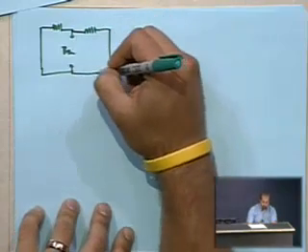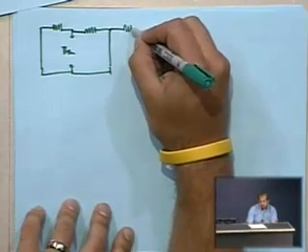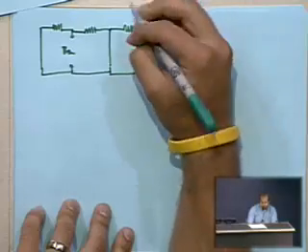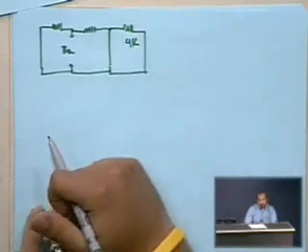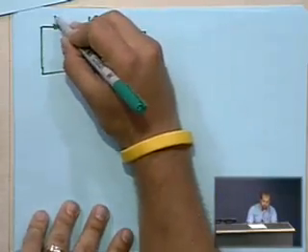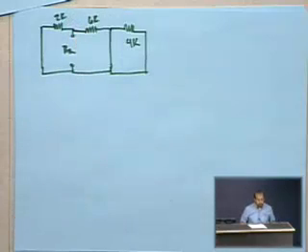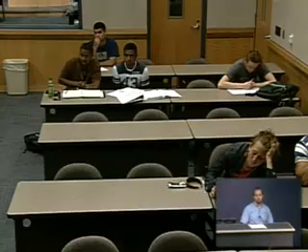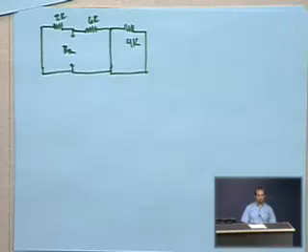The switch is closed here. For good measure, we'll stick in that 4K resistor, but that guy got shorted out anyways, so we can ignore him. We've got the 6K resistor here, we've got the 2K resistor here, and this is kind of weird. What is the relationship between the 2K and the 6K resistor? They're technically in parallel, and it almost doesn't look like that.